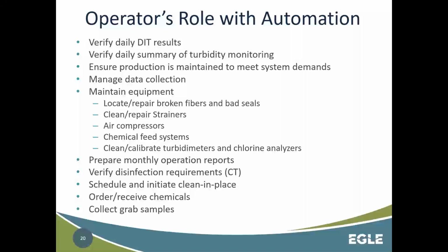Of course, there's the usual data collection an operator would need to do, maintenance of equipment, and there's specific equipment with membrane filtration, preparing MORs, verifying your disinfection requirements, your CT, scheduling and initiating your clean in place, ordering, receiving chemicals, and collecting your samples. So still plenty for the operator to do even at the automated system.